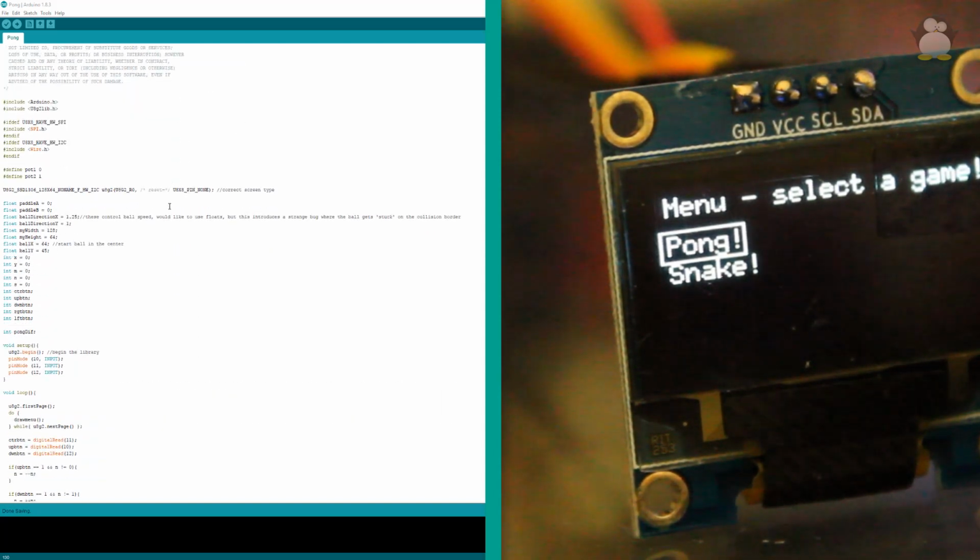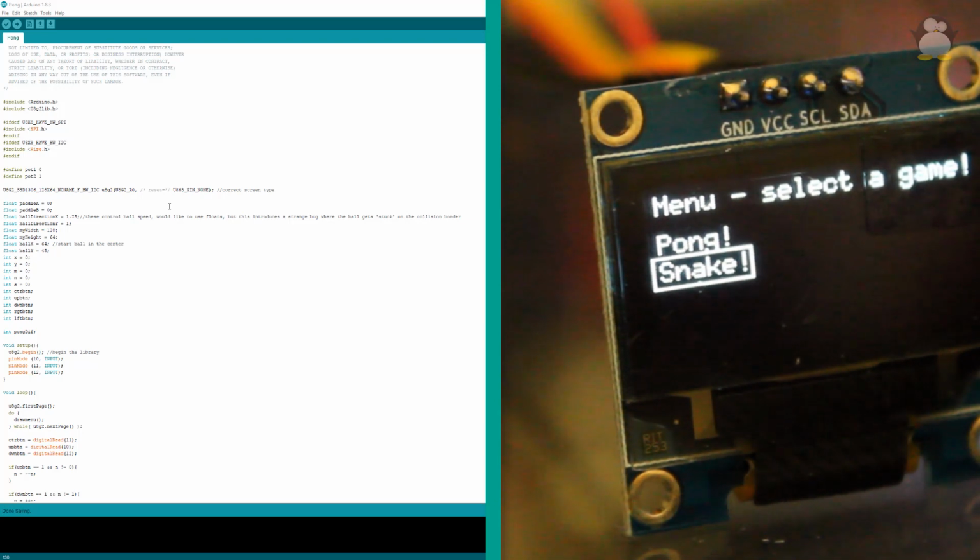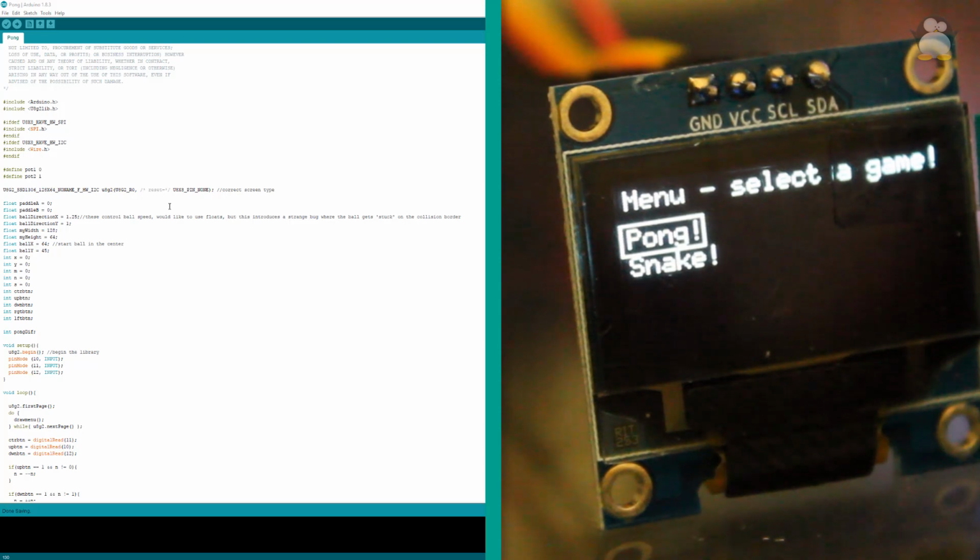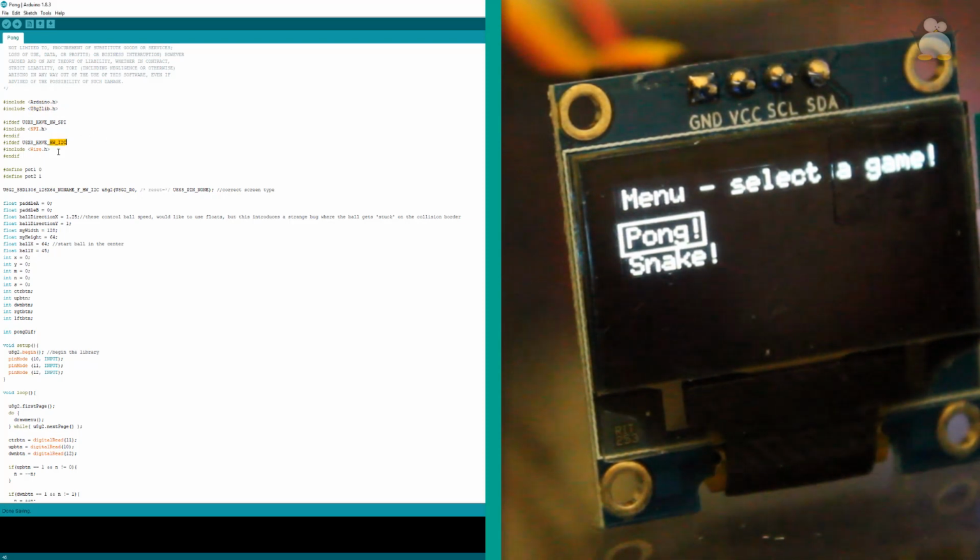I'm only going to glance through this code very quickly in this video so as not to take too long overall, but I may well release another video that goes into more depth on this code if people are interested in that. So to quickly go through everything, obviously we include the Arduino library and the U8g2 library, and then we're using hardware I2C, so we include the wire library to enable us to do that.